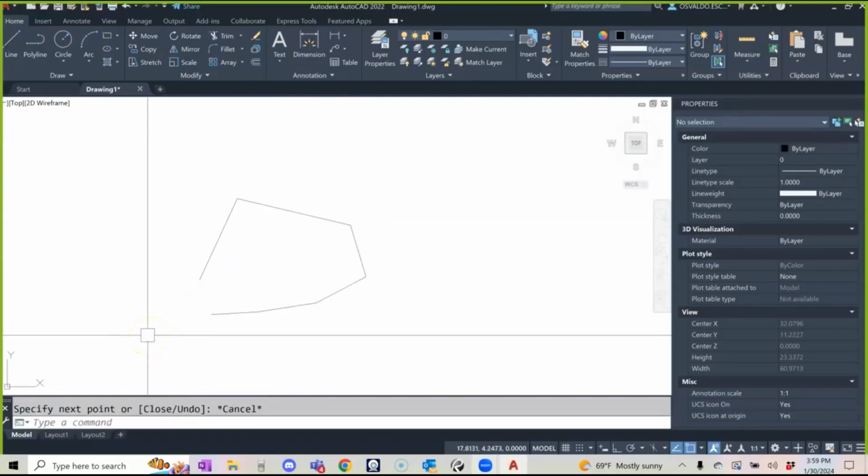You guys will notice that if I draw a couple of lines, the lines are super thin. And in fact, if you are from the back, that's why I placed that monitor on the back, by the way, to see it better. But it still might be a little bit too deep for you to see, so I need to change the line weight. How do I make my lines pop up so I can really show them to you? You type line weight. Really, just type it, line weight.